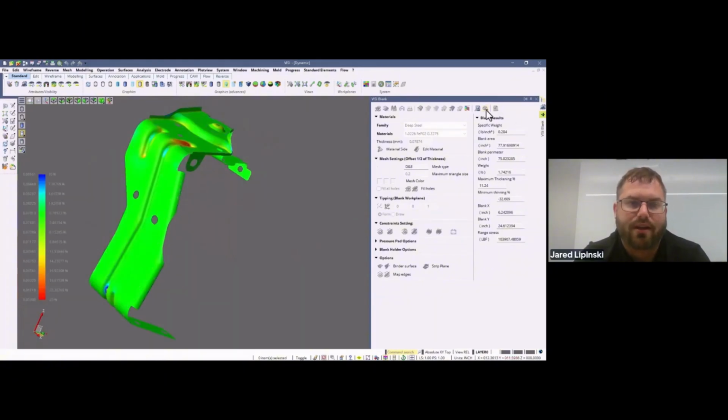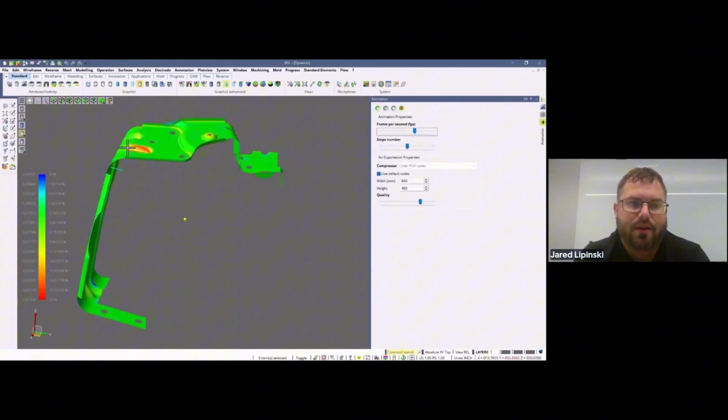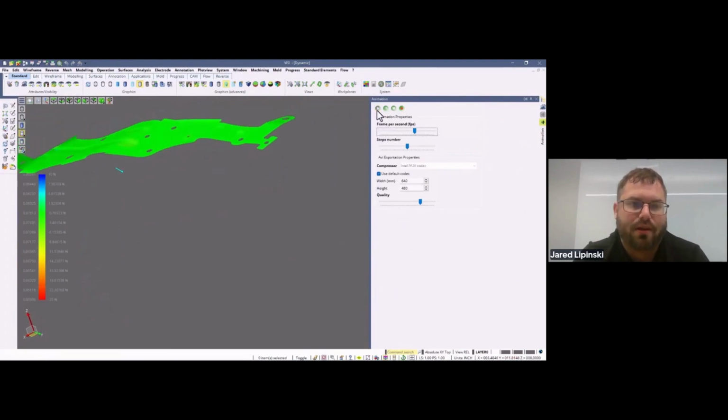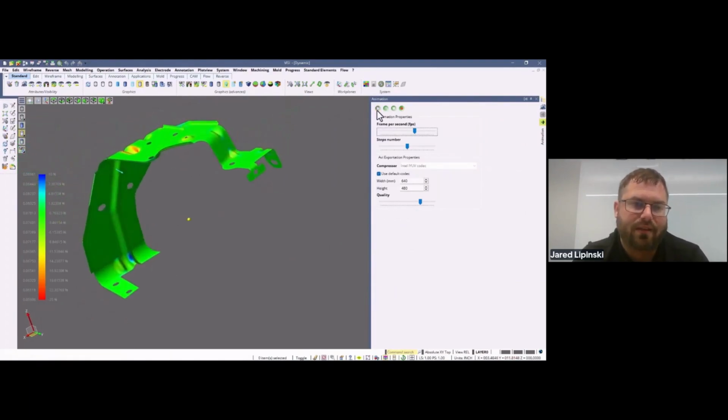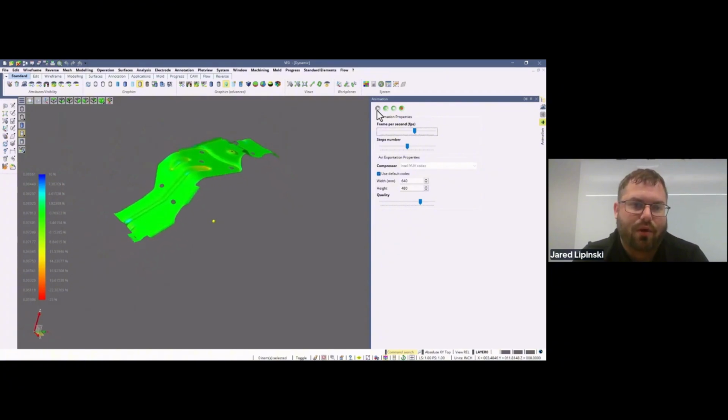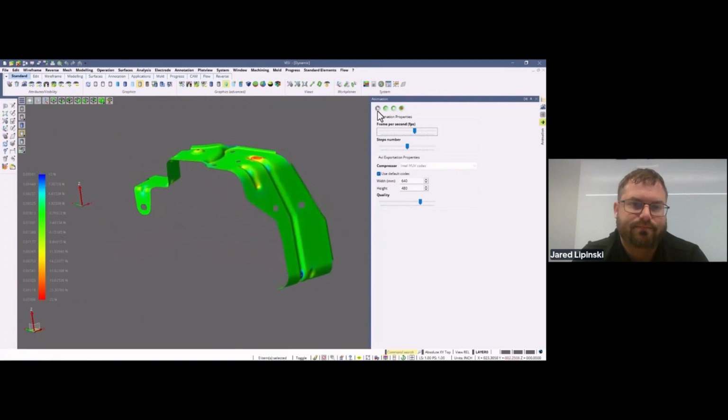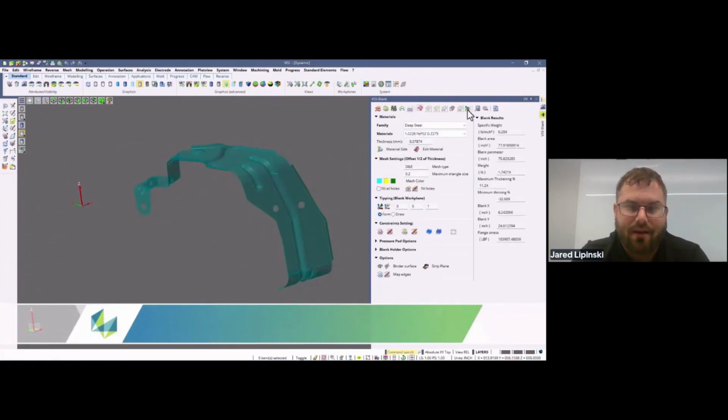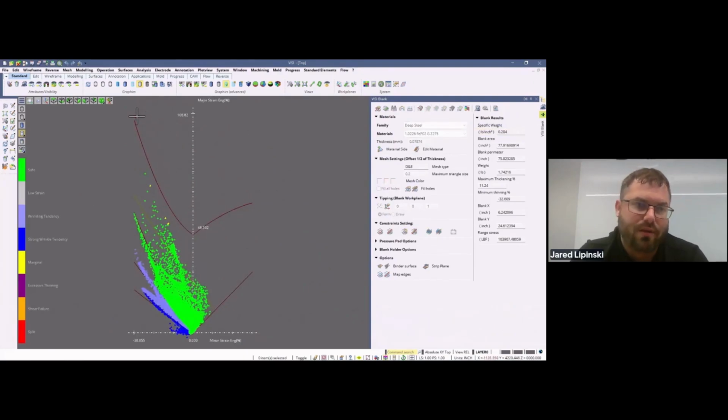Along with safety zones, we can also animate the part. So you can animate this as an entire form. So if I go ahead and hit play, you can see the simulation of that blank when we're forming the part overall. Additional to the animation and safety zones, we also have the forming limits diagram. This will display a diagram right on the screen showing you the progression and where you could have any kind of split tendencies, safe tendencies, any wrinkling as it's going through the entire progression.